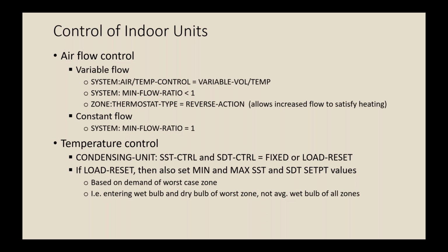For temperature control, there are newer VRF systems that have come out in the last few years that have some more advanced control scenarios where they can do reset of the refrigerant temperatures based on the load in the worst case zone. So that's a way to save energy in the system.